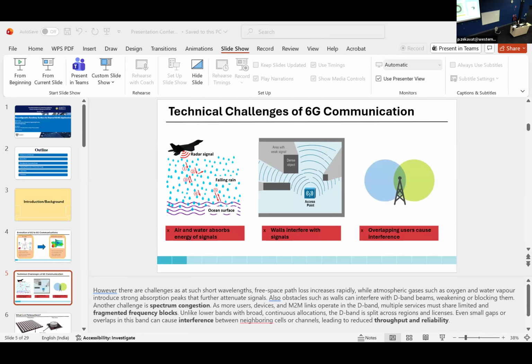Also, PIN diodes control the tuning of this stop band, where they are placed across the intergap between the nested top rings and across the split gap of the bottom circular ring. They can either be turned on, being perfect electric conductors, short-circuiting the split ring resonators, or just be vacuum space.